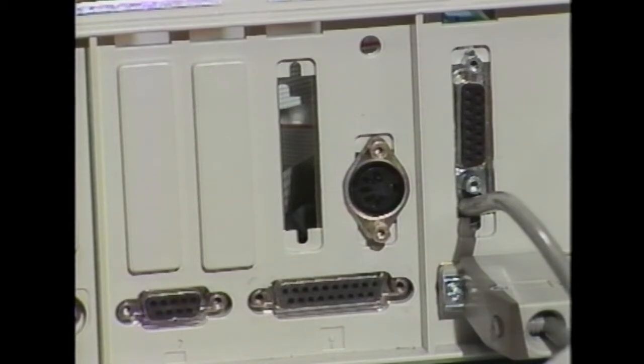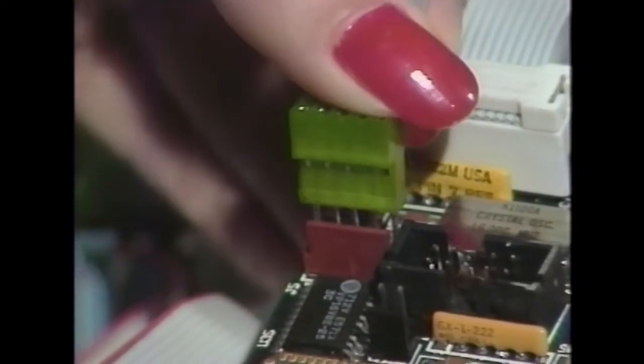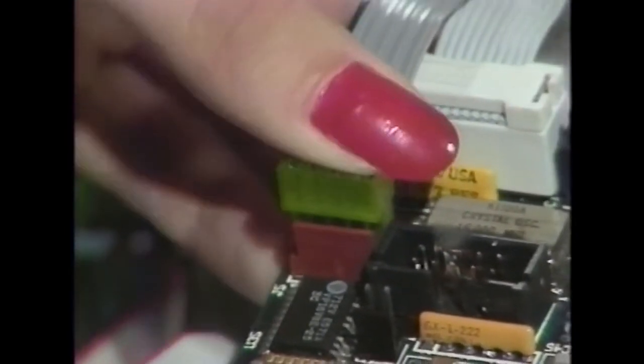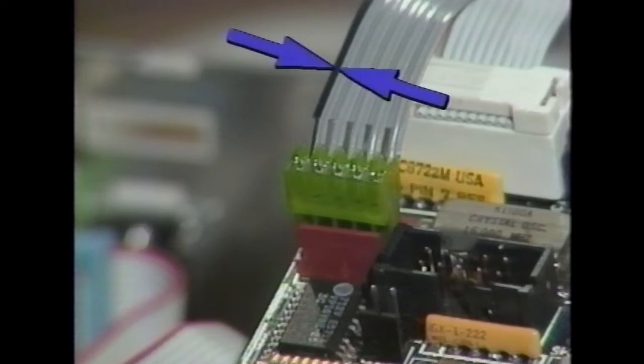Feed the wires into the computer from the backside so that the flange surrounding the DIN connector is outside the backplane. Secure the connector to the backplane using the included mounting screws. Now, attach the flat male connector to the female connector on the PC transporter. The connector was made so that it will fit easily in one direction only. The stripe will be on the top edge.